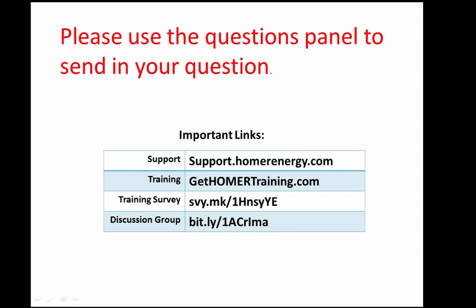Yeah, and just to add on, a lot of the other models that are used when comparing renewable energy technologies just look at a levelized cost of energy without consideration of the fact that the load has to be met in every time step throughout the year. So we not only meet the load, but we actually meet the reserve requirements so that we have uncertainty within each time step. So it's a robust analysis for ensuring that you design a system that meets the load requirements that you've specified.